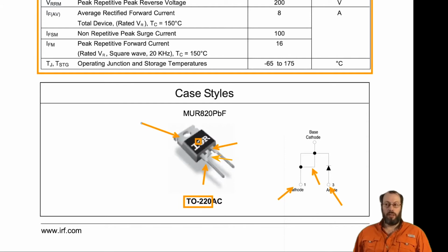The third pin for MOSFETs, but also for diodes, is also electrically shorted to the backside of the device, which is in most cases metal. Sometimes it's covered by a mold for isolation purposes, but this backside is where the die is mounted on to actually get rid of the heat and have a good heat conduction to a potentially attached heatsink surface. Also for mechanical mounting purposes, there is a 3 millimeter hole on the backside here.